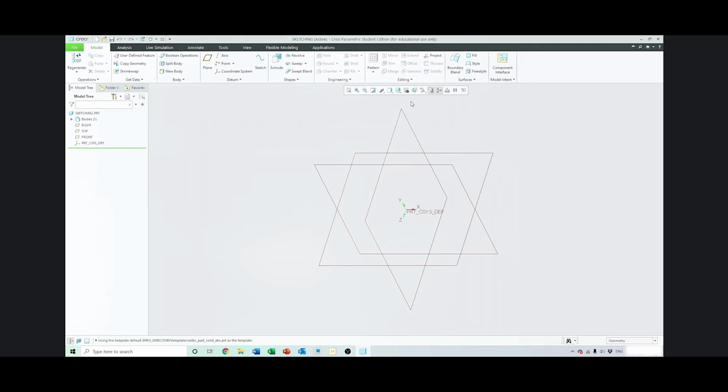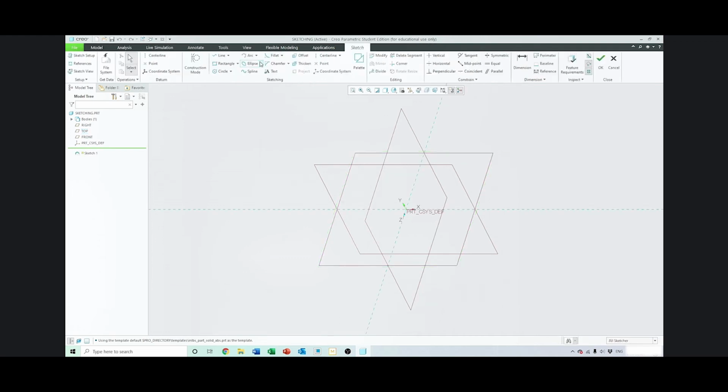So when starting with a new sketch, the first thing you need to do is you need to orientate that sketch to one of these planes. For this, let's just choose the top plane. Once you have it selected, you'll see that it's highlighted in green, and then you go ahead and click on Sketch. And now you'll see that we have entered our sketch mode here, and you'll see that the top toolbar has altered to show now all the various tools that we can use to alter this sketch. The main body of tools that you'll most likely be using are within this sketching tab here.